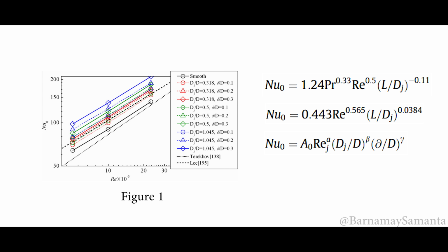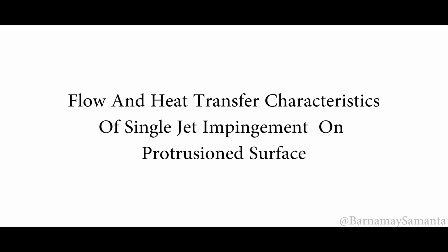The variation of stagnation Nusselt number is obtained through the coefficients in the above correlative equation and the figure. Stagnation Nusselt number is higher with larger protrusion relative depth, jet to protrusion diameter ratio and jet Reynolds number. Furthermore, stagnation Nusselt number on target surface with protrusion is higher than that on smooth target surface. The distance between protrusion dome and impinging jet nozzle gets smaller when the protrusion relative depth increases, so the heat transfer in the stagnation region is improved significantly. Average Nusselt number of protrusion.